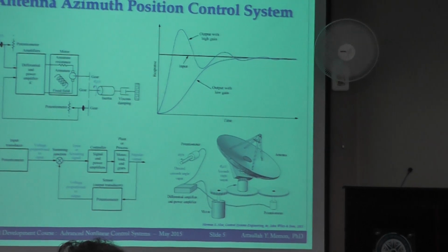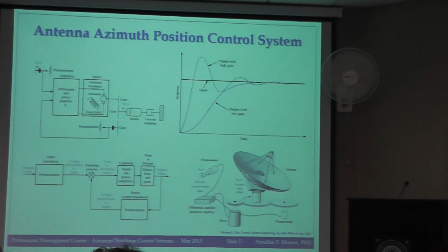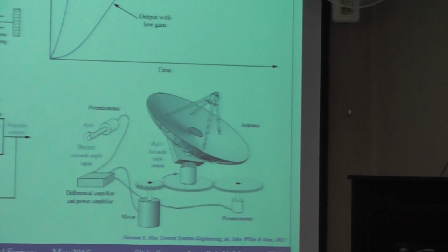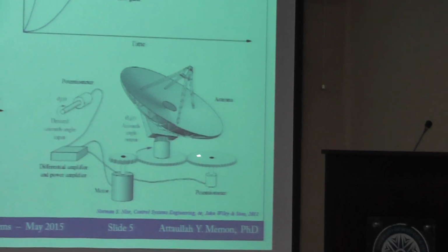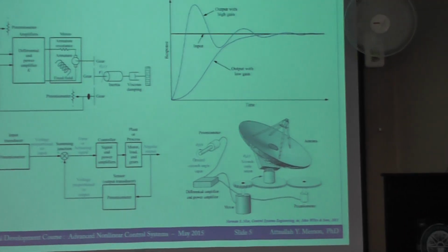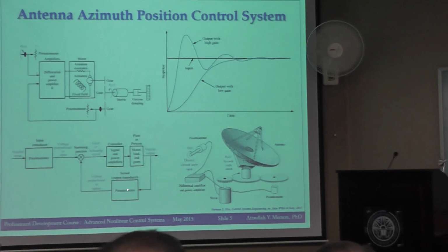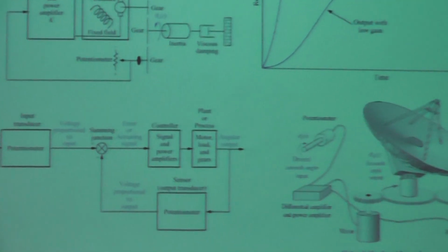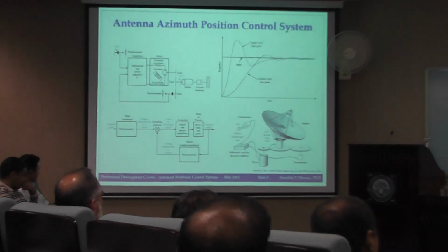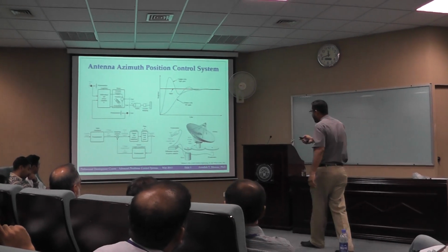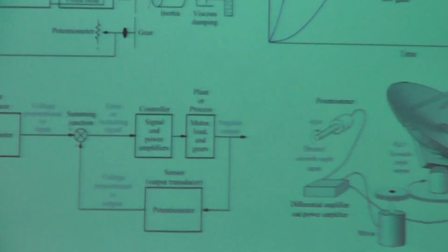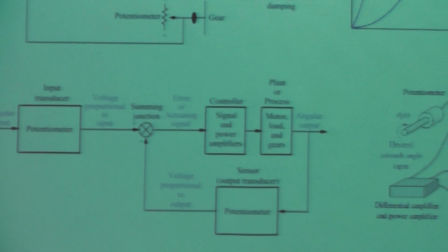And this is that one example. I have this tracking system, and now why am I showing this picture? Because I want to come to this part. Every individual component here has a model. Every individual component has a model, and that constitutes one of the block diagrams. And every individual block may have nonlinear phenomena coming in. Okay? So it's not that only the plant will be nonlinear. It may be that the actuation is nonlinear. It may be that the sensor is nonlinear.